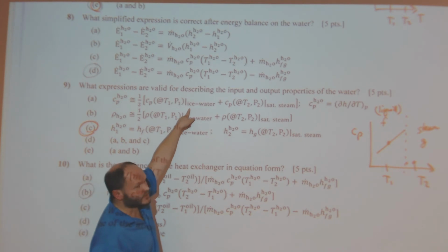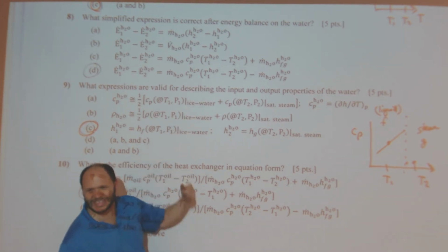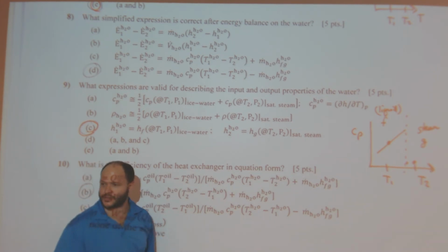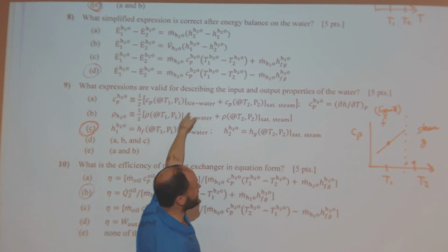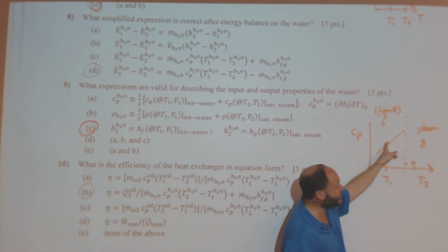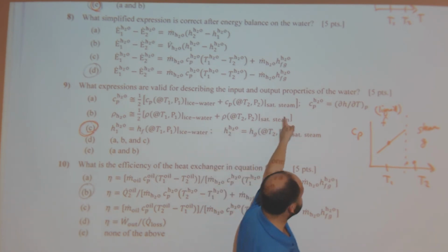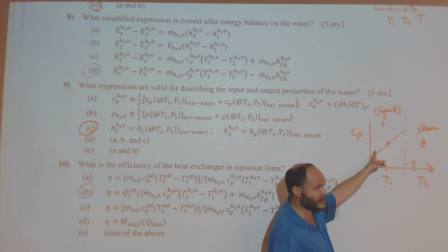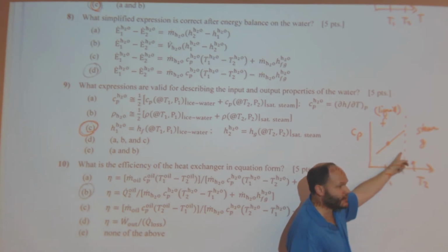Ice water, so water at 0 degrees C. It's not really ice, it's just water at 0 degrees C. And then saturated, I can't take the average value between these 2 points here and here. I can't say Cp of that leaving is approximately equal to this plus this divided by 2, which would give me something right there, because this is a different phase.